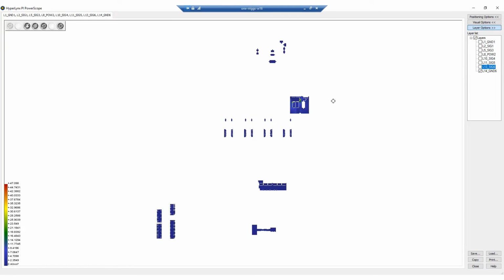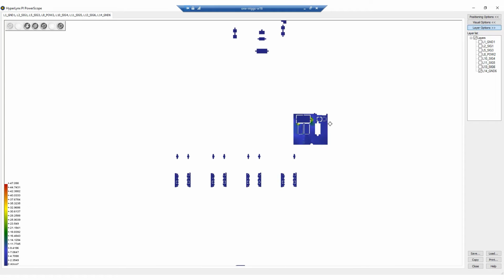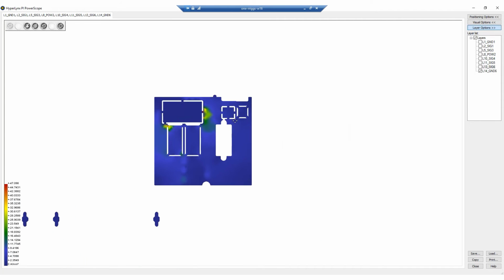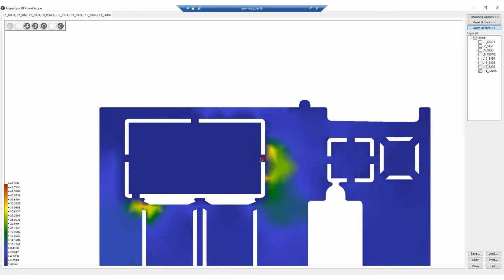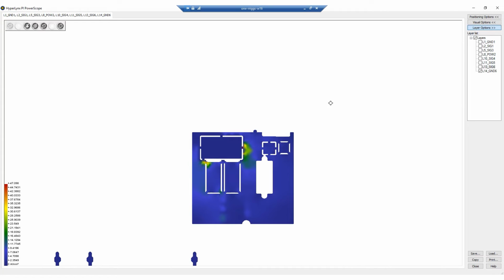The thermal ties are too small in this area and need to be adjusted by the PCB designer. The thermal tie size needs to be increased. This is a very common issue and it's easy to fix, so as far as finding problems with simulation, this is one of the easier ones to correct.